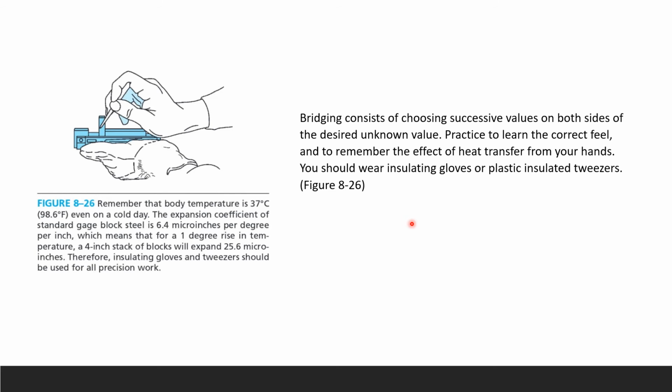Okay, think about your gauge block surfaces, they are at the molecular level. These surface precisions are beyond what we can see with our eyes or feel with our hand. Therefore we have to follow the rule and be so careful about the heat transfer. So it's definitely recommended to wear them, and they will make you wear them if you get the job there.